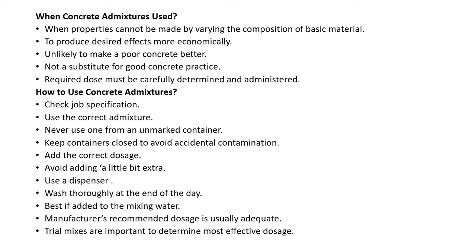How to use concrete admixtures? Check the job specification. Use the correct admixture. Never use one from an unmarked container. Keep containers closed to avoid accidental contamination. Add the correct dosage. Avoid adding a little bit extra. Use a dispenser. Wash thoroughly at the end of the day.